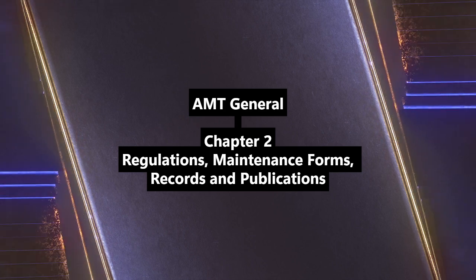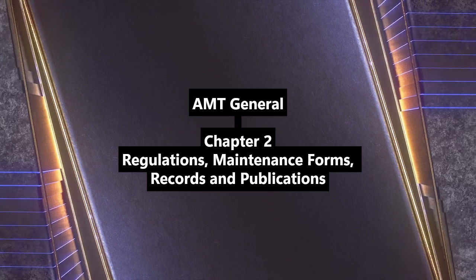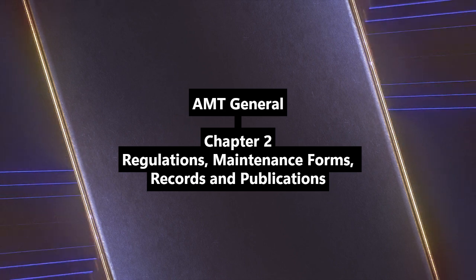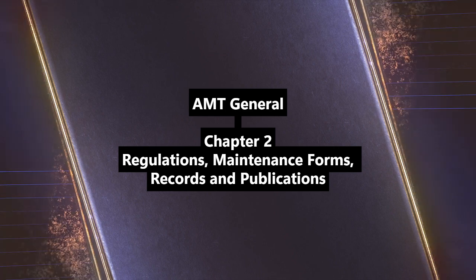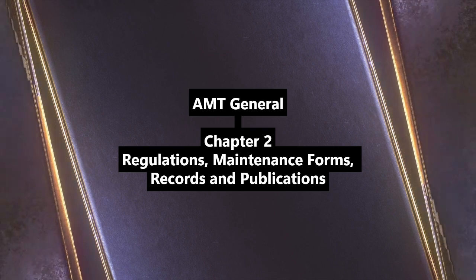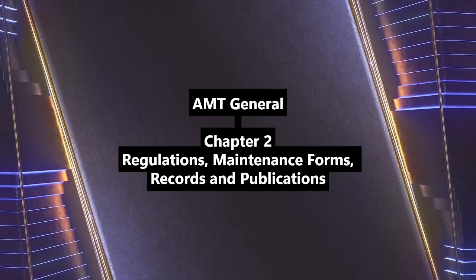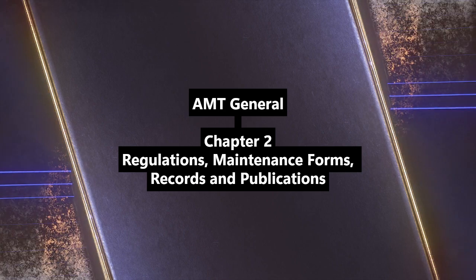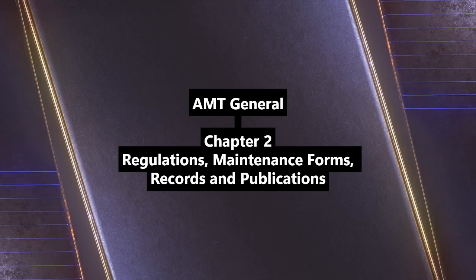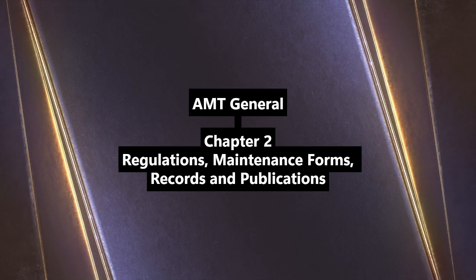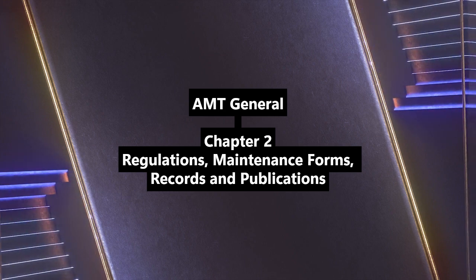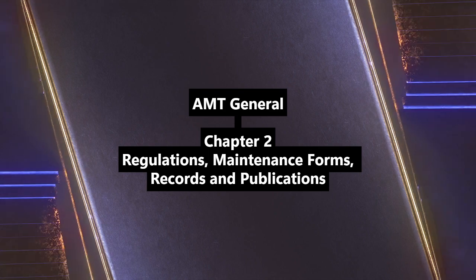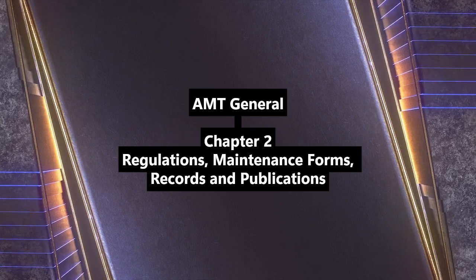Definitely. Now, Subpart E: maintenance, preventive maintenance, and alterations. Section 91.401 just clarifies that some parts of this subpart don't apply if you're operating under Parts 121, 125, 129, or 135, because they have their own, often stricter maintenance rules. Okay, Section 91.403, General. Whose responsibility is airworthiness? Primarily the owner or operator. They are responsible for maintaining the aircraft in an airworthy condition, including complying with all ADs. Does the FAA notify owners about ADs? Yes, they typically send ADs to the registered owner, and all maintenance must follow Part 43, the manufacturer's maintenance manuals, and any mandatory items from ops specs.